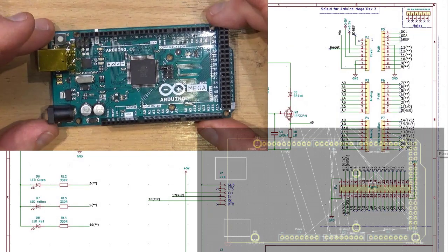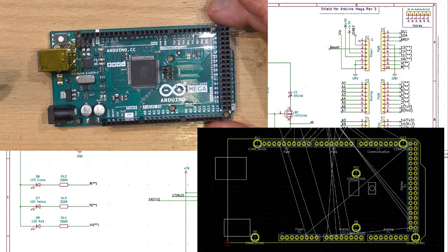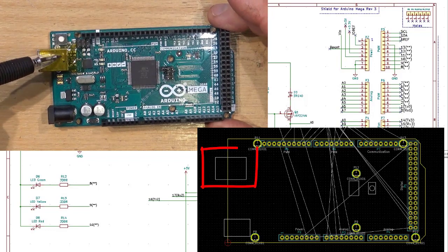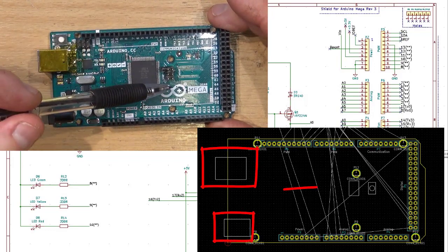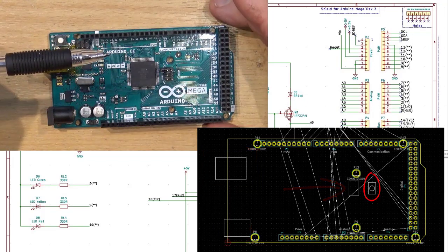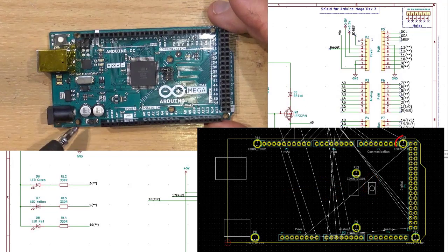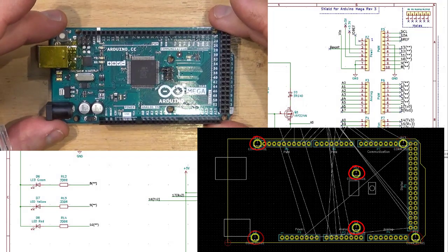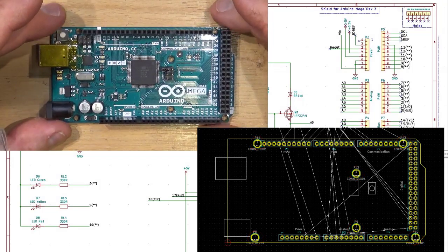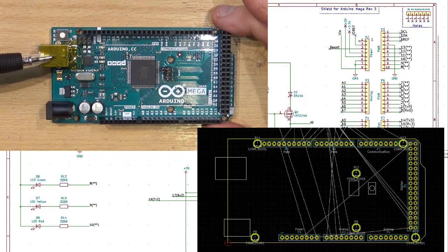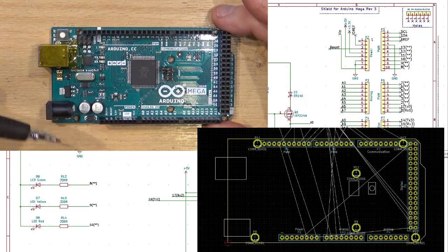Okay, so our template PCB has some shapes already on it for the USB socket, power socket, these jumpers, and I'm not too sure what that's there for. Also some holes to mount it. So I propose to do two things. Firstly, put long enough headers on so that I can get component leads in this area of the board without them hitting the sockets.